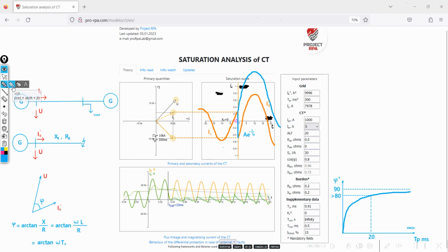The projection of the load current phasor will also result in a sine wave. In our representation, however, we draw it to the left of the amplitude axis, since it represents the state of the network before the fault occurred. What is important here is the fact that at the transition from normal operation to short circuit current at time 0, the instantaneous values of the load and short circuit currents are not the same.